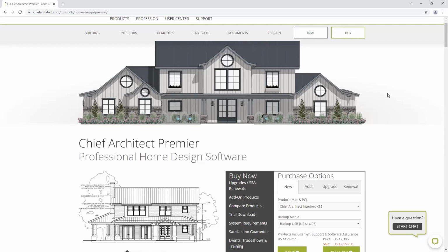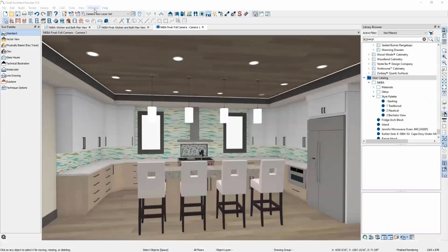Okay, and then from Katie, in X13 under my rendering techniques, the physically based rendering does not say ray trace next to it. She says, when I open the technique options, like use ray tracing is checked, but it's not allowing her to use that option. She's not sure what she's doing wrong, but is that a forum question? So there are a couple things there. She could be using the Mac version, which doesn't have the specific ray trace capability of it. So that could be one culprit. The second thing is to use this physically based ray tracer, it typically requires a newer video card. It could be that her system just doesn't have one of these video cards to perform the advanced ray tracing. So that's kind of the two things I can at least guess at without having a deeper conversation with her.